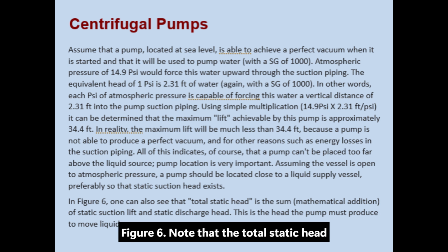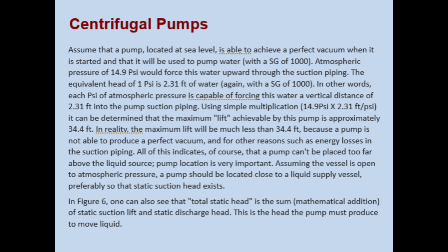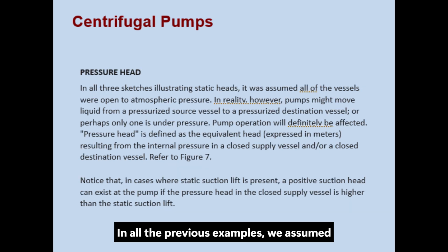In Figure 6, note that the total static head is the sum of the static suction lift and the static discharge head. In all the previous examples, we assumed that the vessels were open to atmospheric pressure. In practice, however, pumps often move liquid between pressurized vessels. Pressure head is defined as the equivalent head resulting from the internal pressure in a closed supply or destination vessel. This additional factor directly affects pump operation.